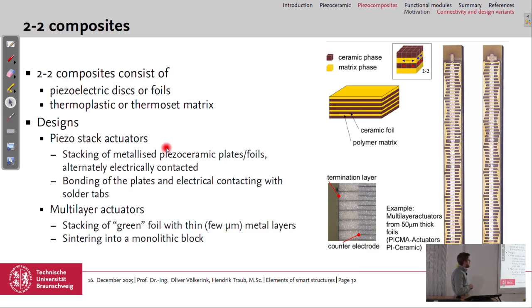You can manufacture it in two ways: stacking of metallized piezoceramic discs and connecting them alternately, so you have composite discs with electrodes on top of each other, and then you just stack them, bond the plates and solder the tabs at the side, or you stack green foils, so not sintered foils yet, with metal layers, and then sinter the overall stack together with the electrodes to build up the stack.